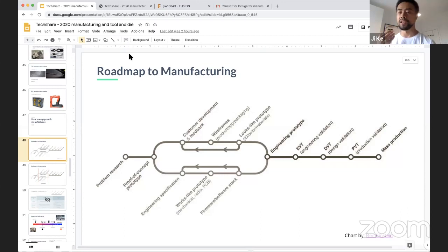And if it's IP ratings, you probably want to test it with IP67: put it under water, put it under rain, see how dust is going to affect it. Probably want to test the temperature ranges, all those kinds of stuff, right? On top, of course, the core functionality, but the core functionality is probably already tested as an engineering prototyping phase, right?